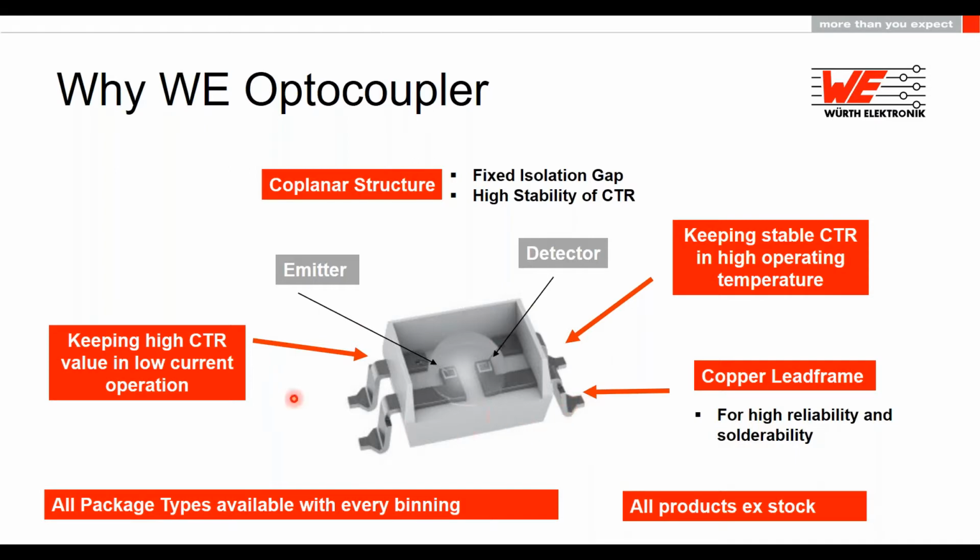And as I showed you in the slides before, we keep a high CTR value also in low current operation. So if you only apply 1 milliamp, you will also get a high CTR value. One of the requirements was also to have a stable component, and this can be guaranteed because we have a stable, high CTR during high temperatures and over the whole temperature range.